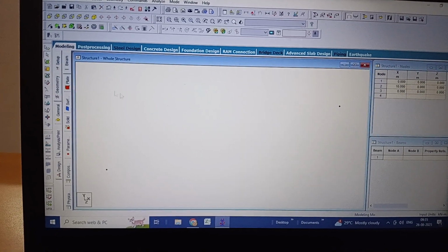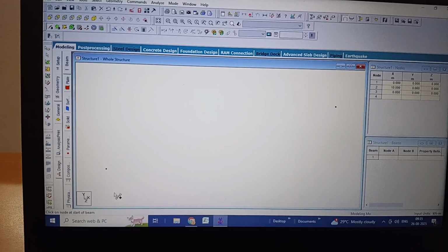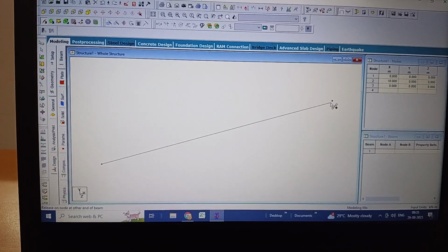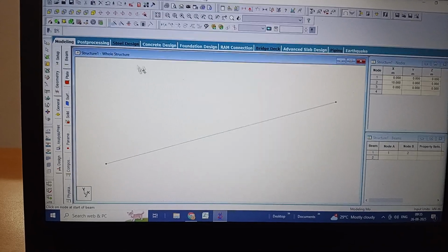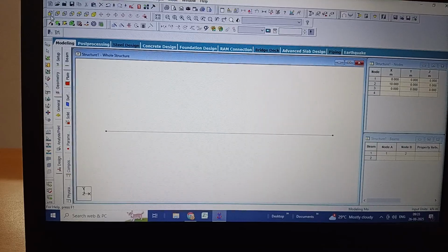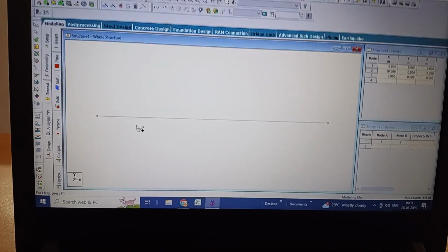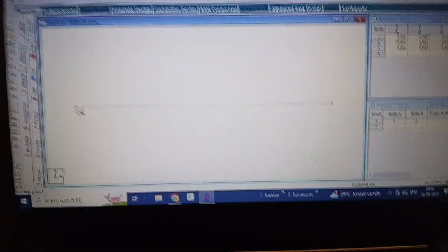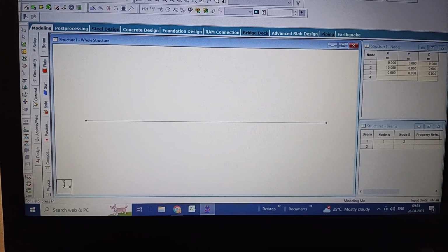So you select the Add Beam cursor. Next, add these 2 points. Next, you click the view from Z. So this is a beam. There are two nodes and one element. So next, go to the General category.